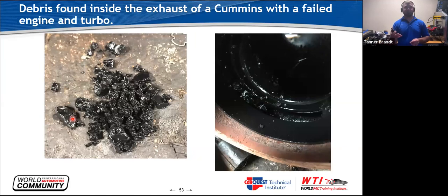When that happens, sometimes you can end up with a situation like this. This is on a 5.9. The engine came apart and blew up the turbo. They put an engine in it and called me to look at the turbo because the turbo wouldn't spin. I went and looked at it. All of this debris not only was in the turbo, but was downstream in the exhaust as well. If they had started it with a new turbo on it, it very likely would have come back up into the turbo and ruined the new turbo.